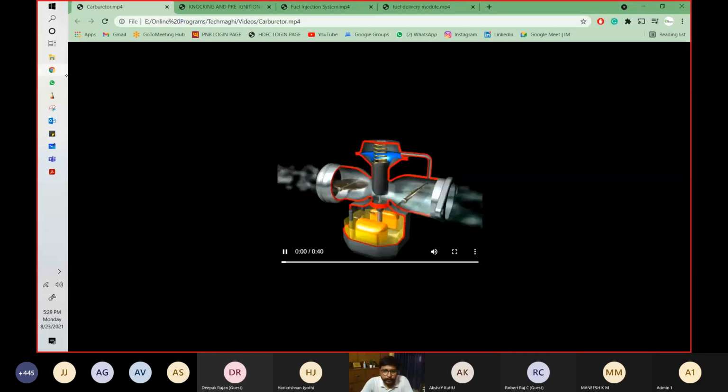You see, this is a carburetor. This is the bottom part of the float of the carburetor, and this is the spring that I showed you, and this is the section that I was lifting or closing. This is how air is coming inside, and over here at the venturi, the narrow part, the air is mixing up with the fuel.